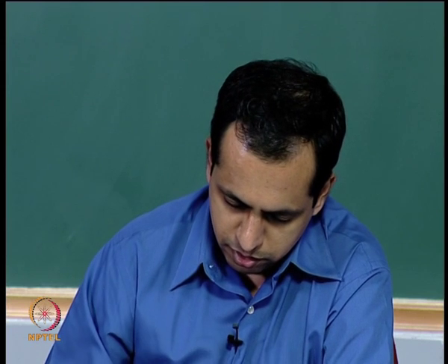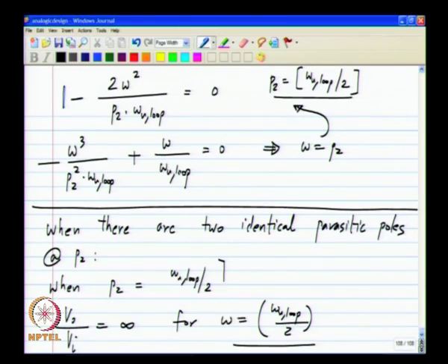Okay. Now, it actually does not matter for what frequency the gain becomes infinity, because once the gain becomes infinity at certain frequency, at that frequency even without an input you will have an output. So, the amplifier becomes completely unusable, because the amplifier is supposed to give you only the input times the gain, it should not have anything unrelated to the input. But if the system is unstable, it will have something that is unrelated to the input and the amplifier is useless.